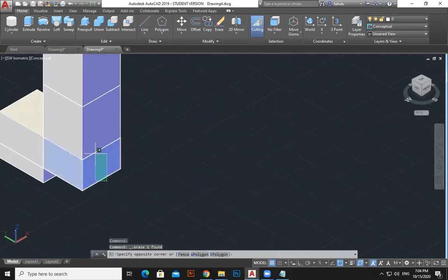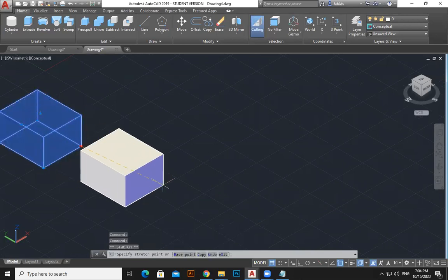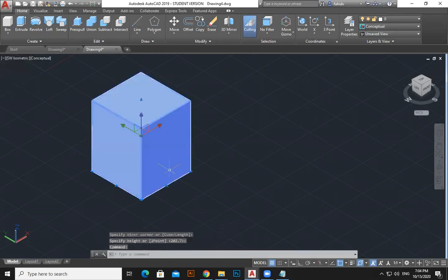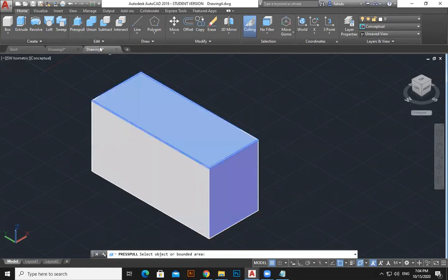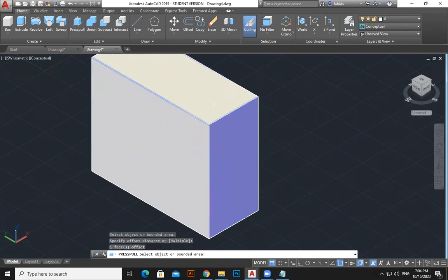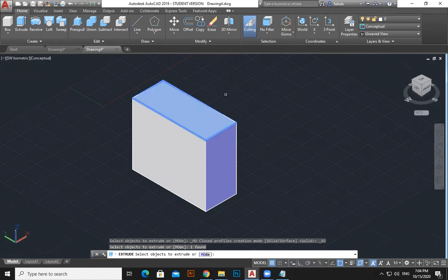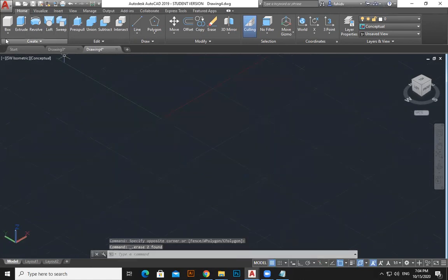If you take a normal box, how are we going to extend it? See here, we're going to extend, right? Create a normal box. If you extend it, this is the same use. We use it with press pull also. Click here and move it. We are increasing the size. With extrude, Control and click here to do it. It will be separate portions. This is separate. So extrude and press pull, I told you.